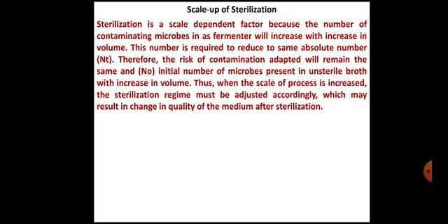Scale up of sterilization means designing a protocol of sterilization at small scale, and designing a sterilization protocol at large scale, because sterilization is a scale dependent factor. So the time temperature relationship and the holding time are going to be different. For a small volume, the holding time is going to be different from a larger volume. And in case of continuous sterilization, the temperature factor is again variable.